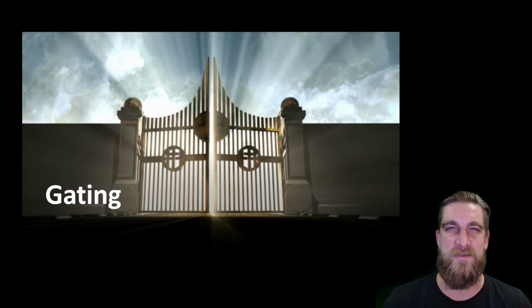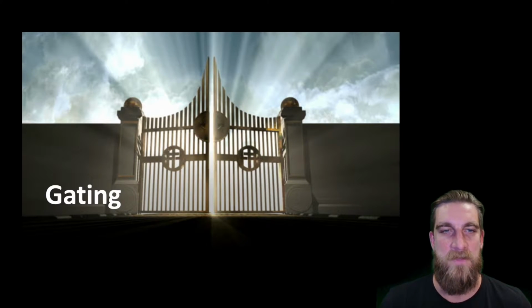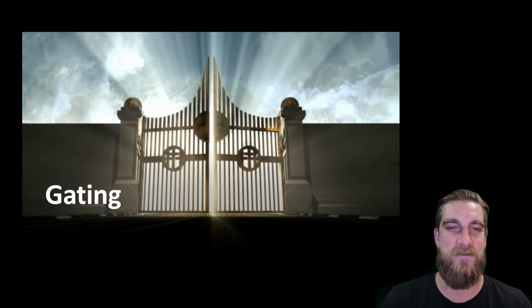So let's just say that we're recording our voice and there happens to be some chatter from some other people far away from us or something like that. It's not going to be very loud. So as long as we set our threshold at a particular level, if I'm not speaking and all the microphone is picking up is the people way behind me talking for a little bit, the threshold will not be passed and the gate will not be open. We will block out that incoming sound, and the result will be silence.